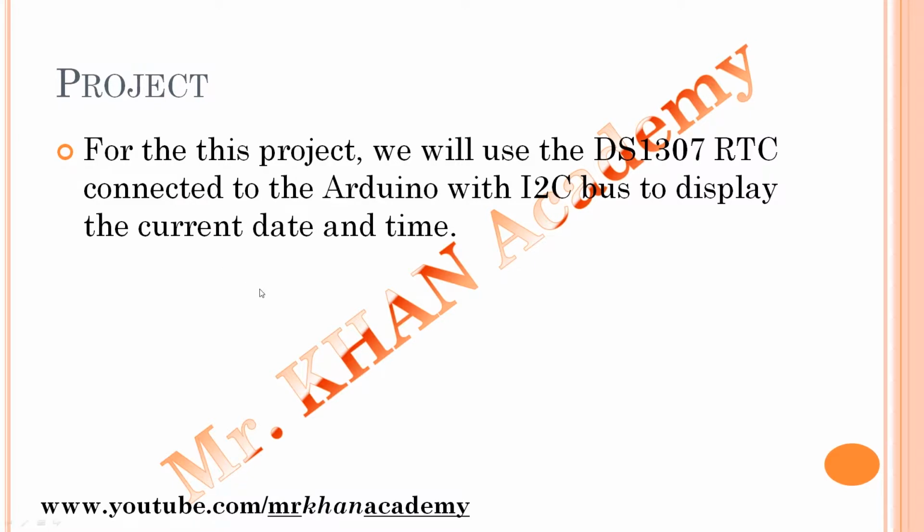Now in this project, what exactly am I going to do? We are using the DS1307 RTC module, which, as I said, is connected to the Arduino with the I2C bus to display the current date and time. That much only we are using on this bus line, two-wire communication. We retrieve the data from the RTC and send it to the Arduino, and from the Arduino, with the help of serial communication, we send it to the serial monitor. That is the task of our project.